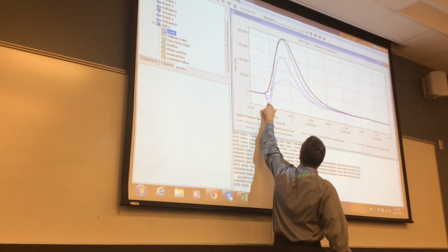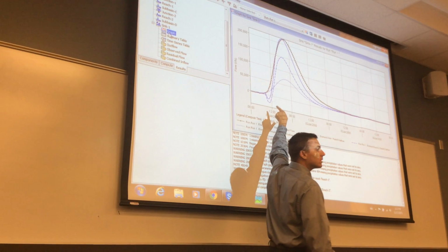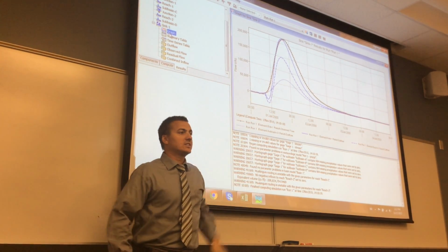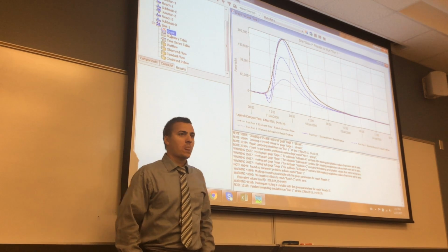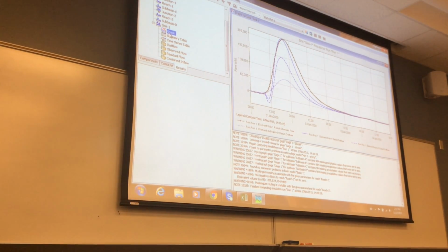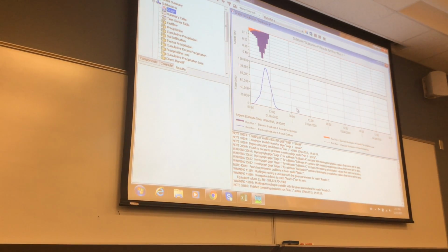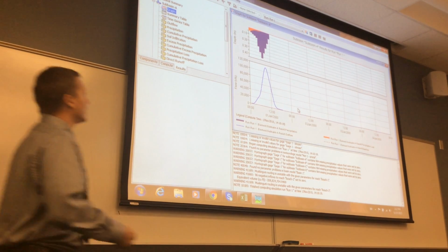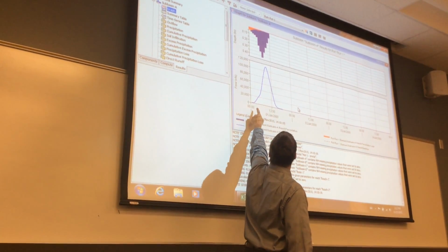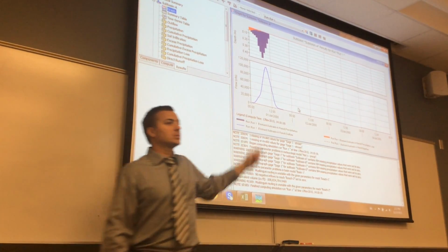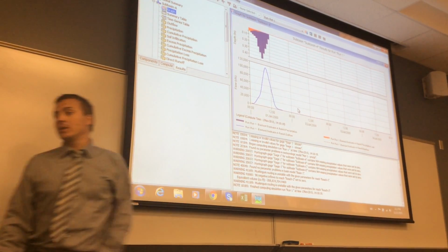And here's where we're getting some instability here. Does this make sense? Yes? So we can explore the results per subbasin. If I go to subbasin A, here's my rainfall runoff response. That's the rain. That's the flow, that's what's coming out, and that's your infiltration right there.